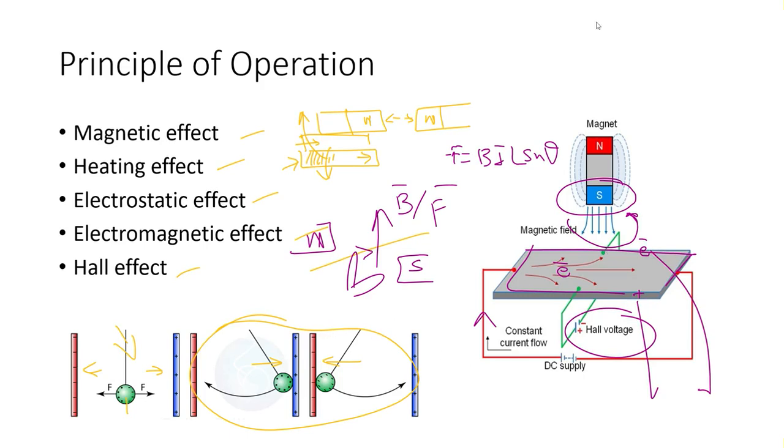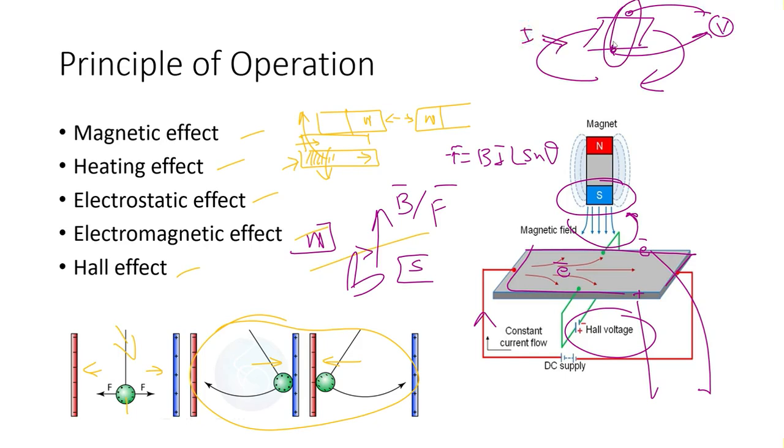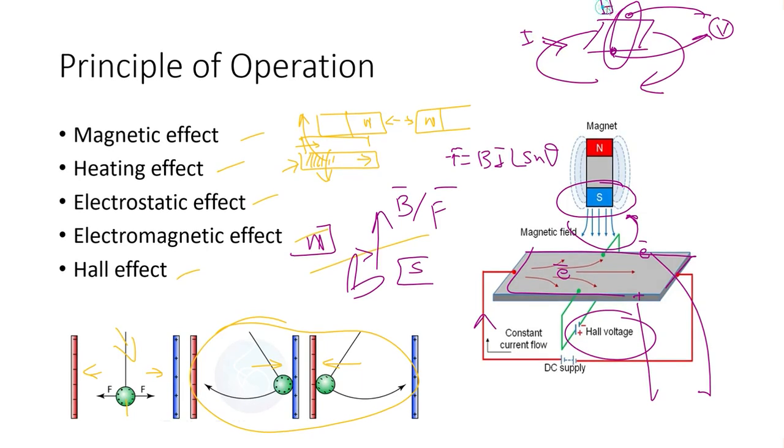In Hall effect, we place a plate, we pass current through this plate, and at 90 degrees to that current, we get the output voltage and we measure it. So the amount of voltage developed on these two terminals depends upon either the current that is passing, more current, more voltage developed, or the magnetic force that is being applied to it. So more magnetism, more voltage. Normally this magnetism is kept constant, and only the conductivity of this material is checked by this current.